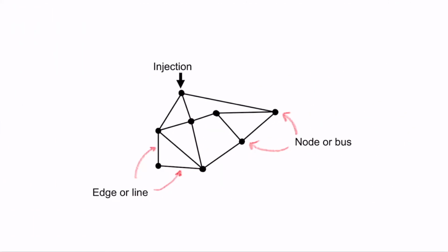In this lecture we are going to study how we compute power flows and how we can formulate them in a very systematic way. So let's start with some definitions. Let's imagine that you have a network, in our case an electrical network. In networks we typically call these parts edges, and nodes the ends of those edges. In a power grid, we classify them as lines and buses. So a bus is basically a node.